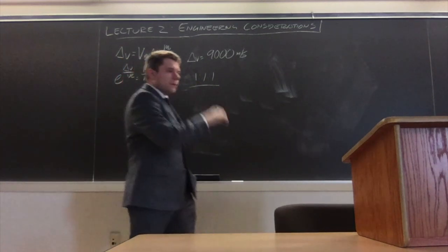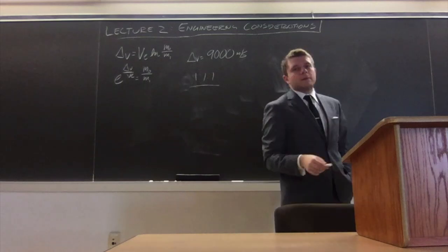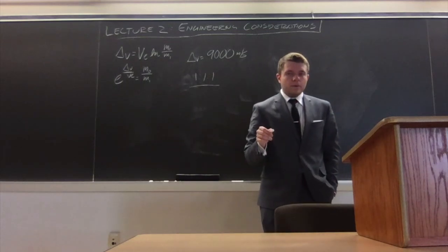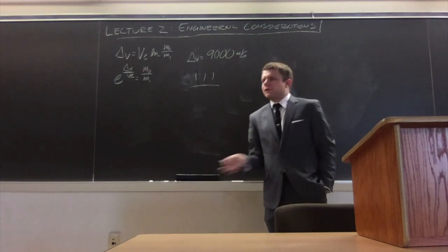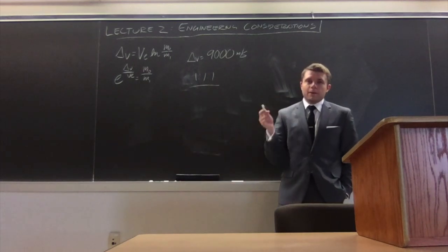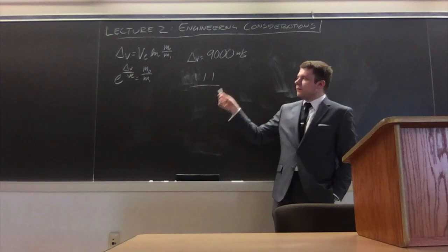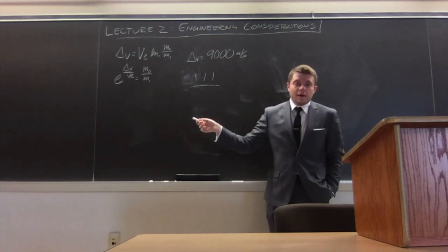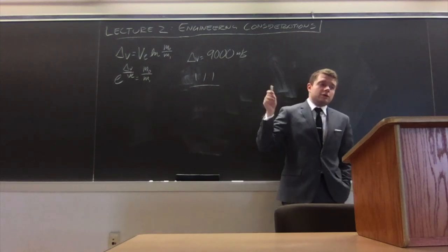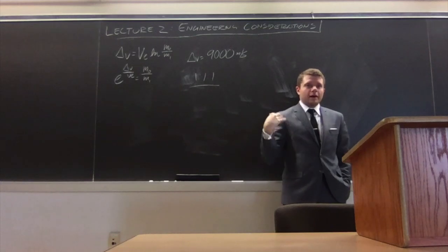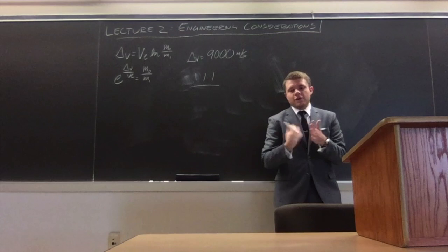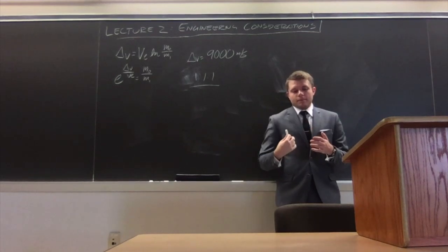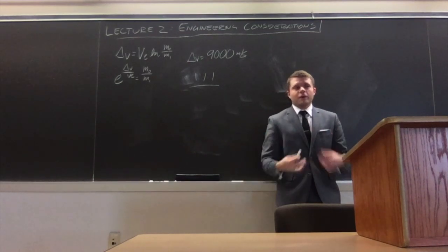And for our purposes, for the first round approximation that we're talking about here for the launch vehicle, we are going to treat it in that way because it's the most reasonable way to treat it based off of what we know of experience. Now, there are caveats to this. One of the big ones is that specific impulse changes with altitude. Rocket engines burning in space can get a higher effective exhaust velocity because there's no gas pressing on the inside of the bell to resist the propellant coming out, so you get a little higher performance.